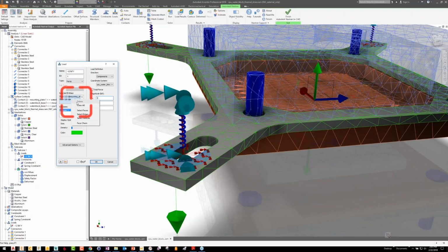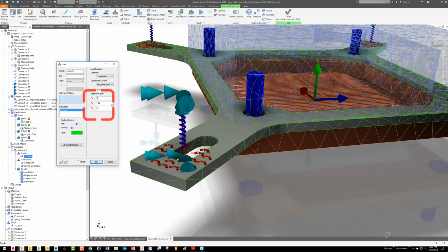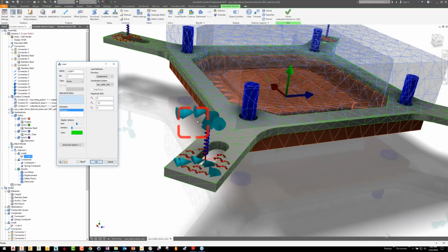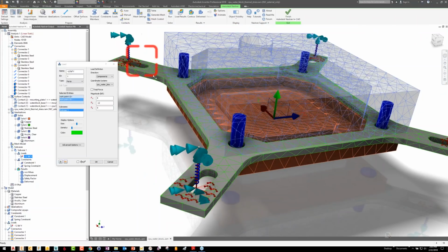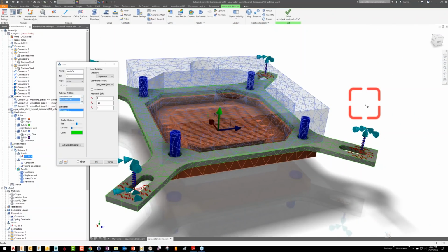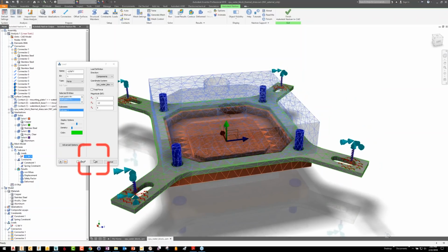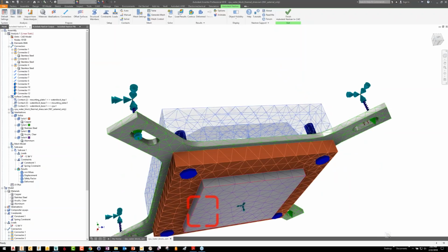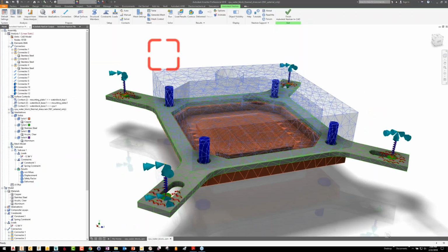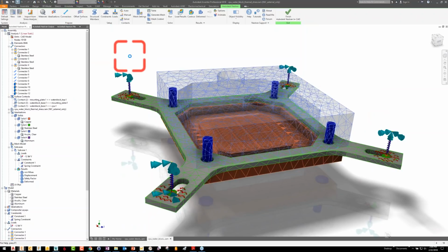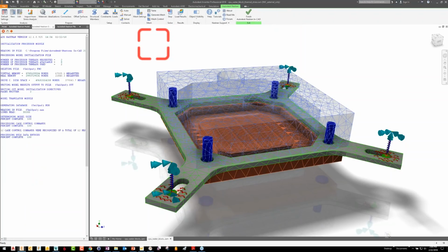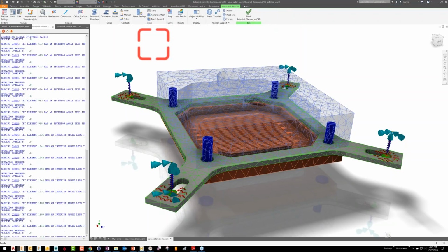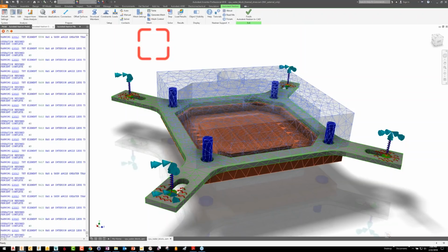So I will clear out the selections I had in there for those pads and now pick the top of each of these springs. So each one of them will get that 12-pound force pushing down on them. Okay. Give it a save. I usually do before I run. If it is going to dump you out, it's probably at that point. So save your work just as frequently as you've gotten used to saving it in Inventor work.